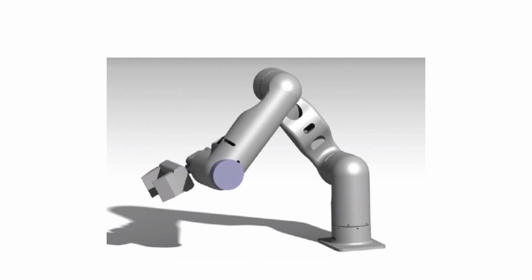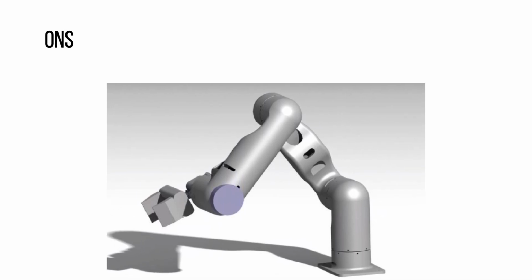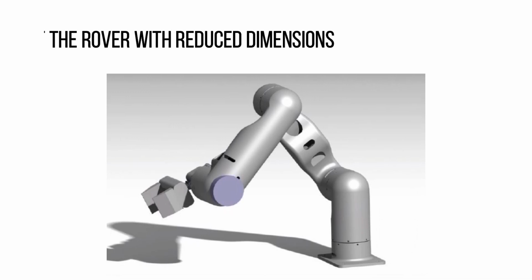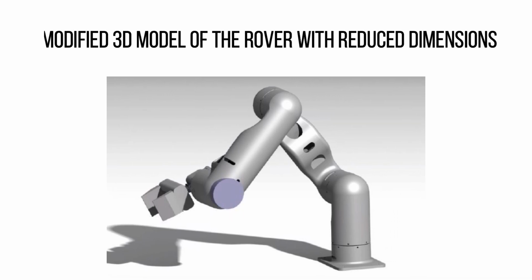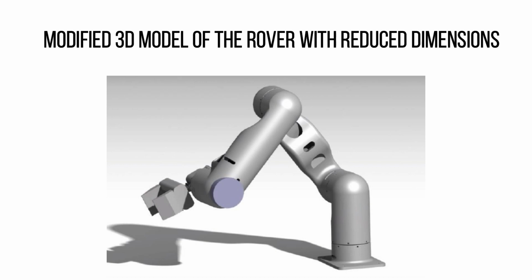Now the torques exceeded. Still, the final design with the modified material is of reduced dimensions, suitable for a workplace, and is moving on motors. The provision for incorporation of the temperature probe is also removed for weight optimization of the arm. The material of the motor cylinders was changed to aluminium and made hollow such that the weight matches that of the actual motors that are being used in the arm.